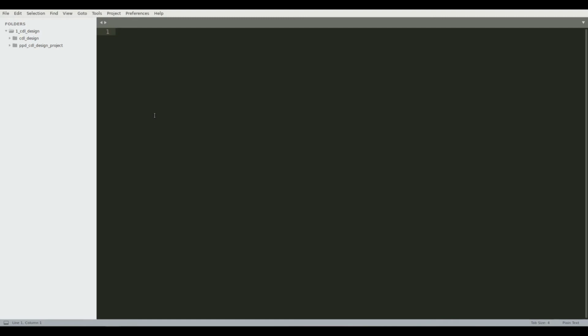Okay, so I'll just be doing a quick CDL design demo for the CDL Standalone Core. As I explained earlier, this is where you have the core that can only run one single network and it's highly optimized. What we'll be using as a neural network is SqueezeNet, trained for person presence detection. So it only detects whether there's a person present in the image or not.